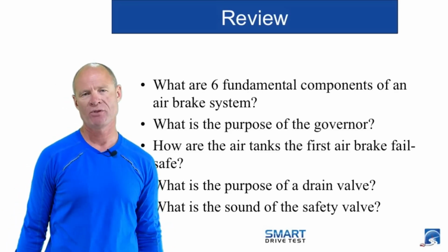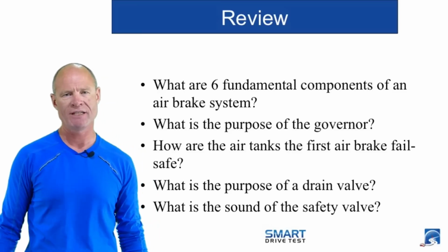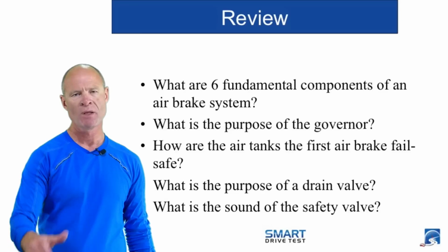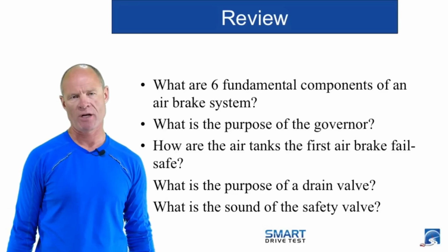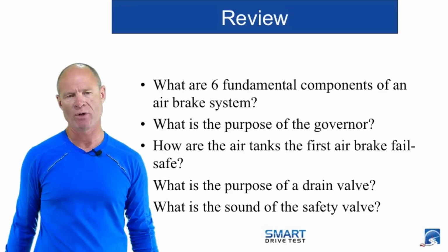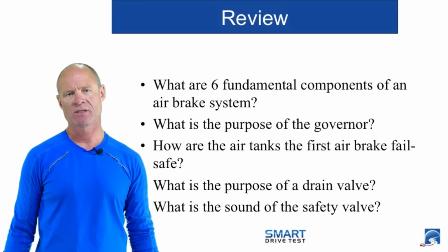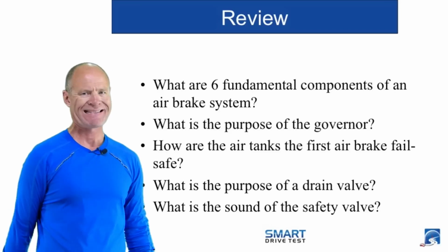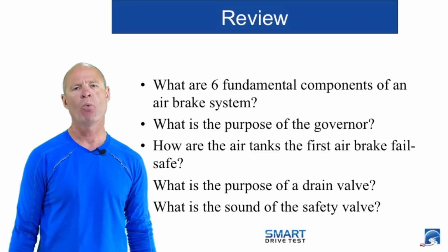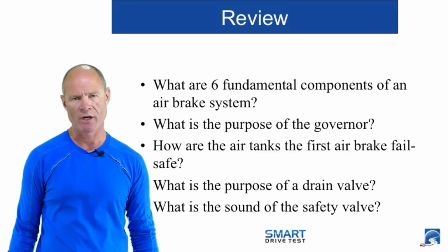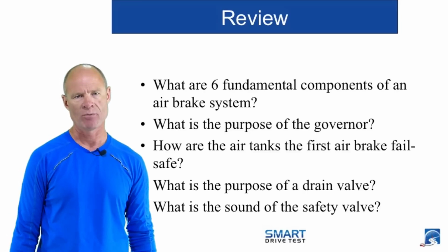Question: what is the purpose of the drain valve? The purpose of the drain valve is to drain water from the air tanks so they don't freeze up and cause damage to the air brake components, and to drain other sludge that is discharged from the compressor, and some of the dirt. Question on the test: how often do you drain wet tanks? The answer to the question is daily. Every day you drain the tanks on an air brake system.